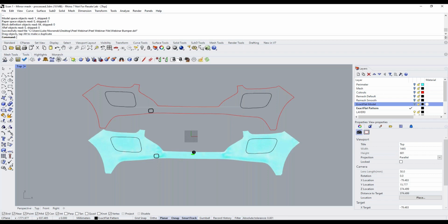So each material in our library has been analyzed at a lab. We've stretched it along the warp, weft, and bias direction to determine how it behaves as the material is being deformed. So I didn't change the material during this demo, but you can choose the material that you're going to use for optimization. And we do have a way you can use our material editor to insert your own custom materials. We do partner up with the lab.